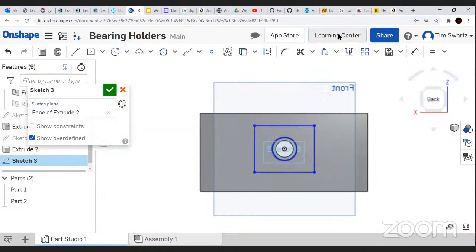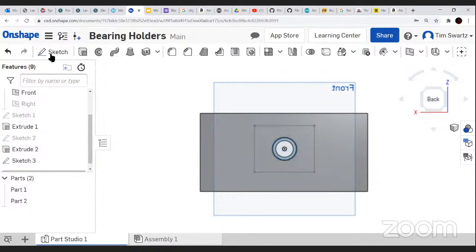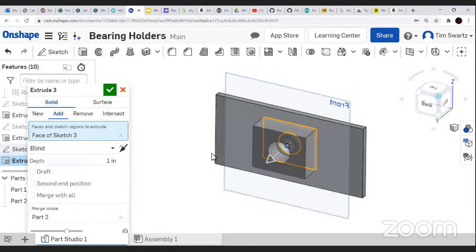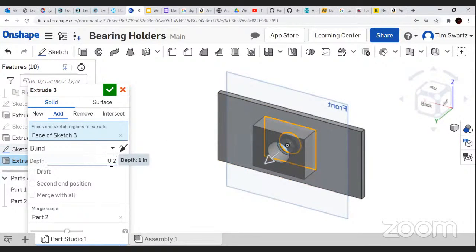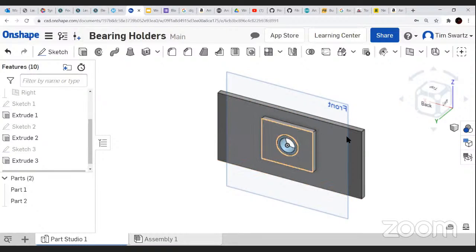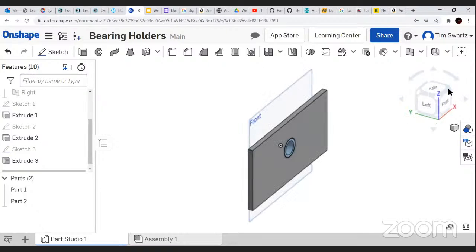And then you could take that, and we'll make this 0.25. And you could just do a lap joint and weld around here and then press the bearing through, and that would take care of that. But there's a few issues that come up with this design.